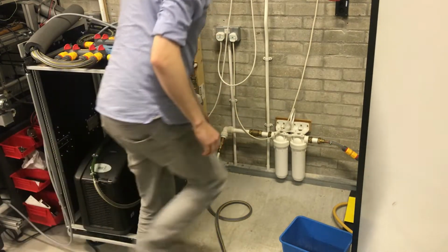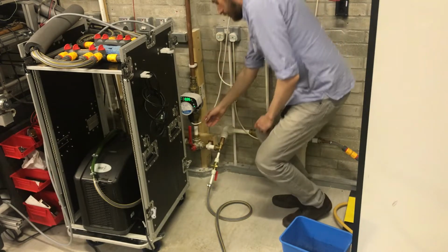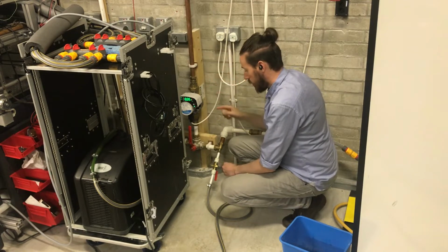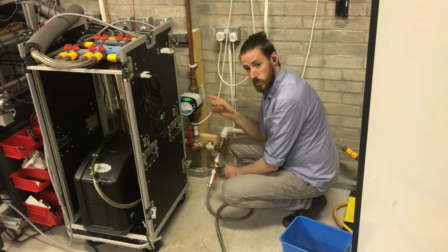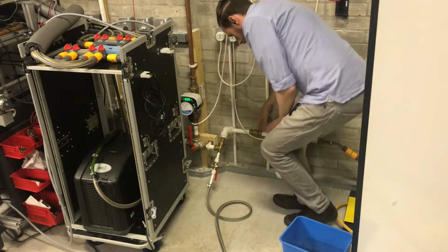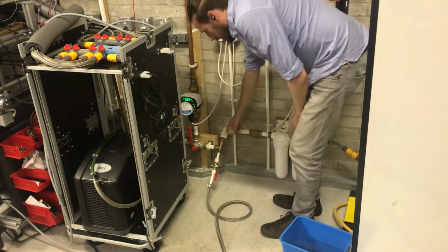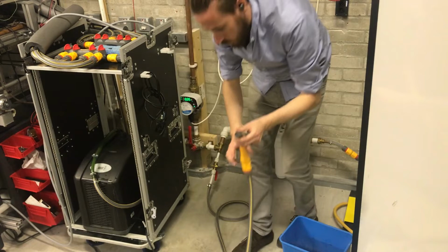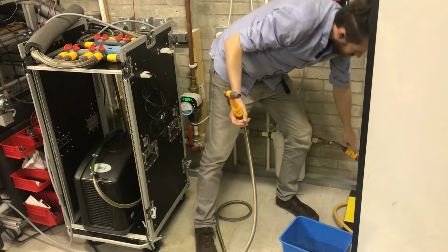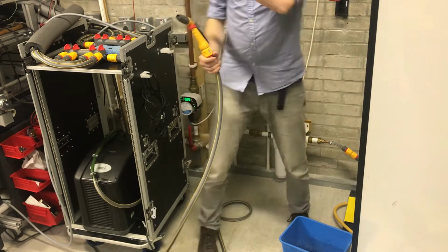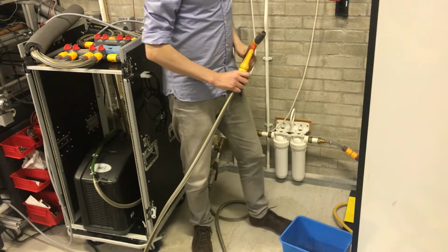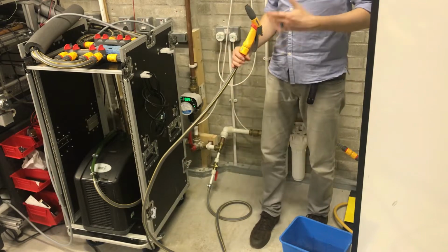The diverting valve here, the selector valve, is selecting where this flow that comes down is going. It can either go that way into the experiment, which would be normal, or it can come this way through this pipework. It can't go back through the filters because there's a non-return valve here, and so it has to go through this hose pipe and will come out to here. The idea is that you can connect this hose to this hose and use the pump to drain down the whole water system straight into the sink to make it a bit easier to clean the system after use. So that's what I'll be doing at the end of the video.